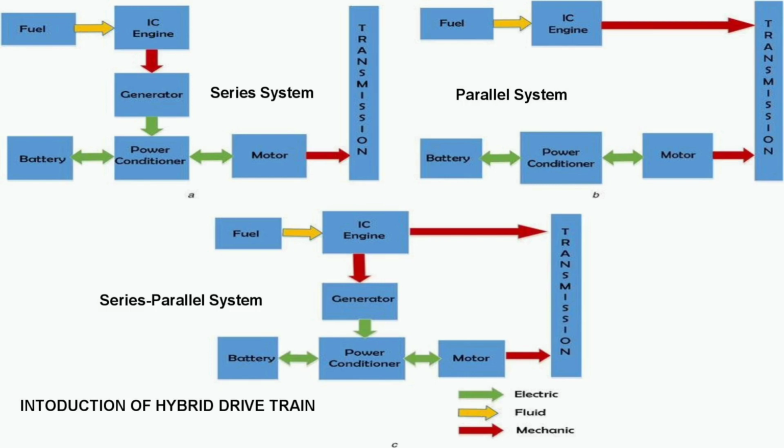The design of power control strategies for hybrid electric vehicles involves different configurations, such as, first, optimal ICE operating point. The optimal operating point on the torque speed plane of the ICE can be based on maximization of the fuel economy, the minimization of the emissions, or a compromise between the fuel economy and emissions. Second, optimal ICE operating line.